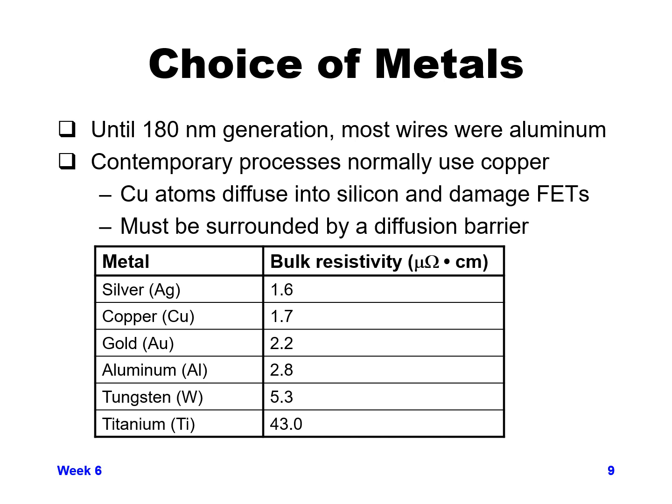But in the latest process technologies, because of the Damascene process, we normally use copper now because we have a way of protecting the silicon from the copper, where copper wants to diffuse into silicon and it would damage our FETs and damage our oxides. But we have a way to put a diffusion barrier in place now, process technology.